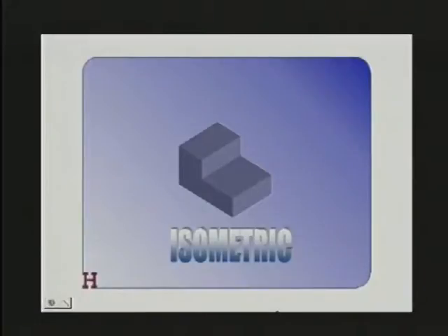Well, there's another way to project 3-dimensional objects onto 2D media to make them easier to view without all the complexity of constructing these changing scale perspective drawings. And that method is called isometric projection. Here again, you see all 3 dimensions of the object in a single view. But in this case, the parallel lines are drawn parallel. And iso means equal, metric means measure, and when we construct this isometric projection, we measure all these distances equally: the width, the height, and the depth of the object.